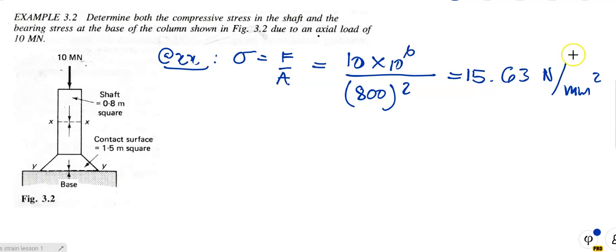There we go. So the stress anywhere along the plane here, along this bit of the shaft of these dimensions, will be that. Have you thought about what it is going to be at YY? What do you think the stress is going to be along plane YY? If this is going to get bigger and that's going to get smaller, we expect the answer to be smaller. That's right. If there's more area, the stress will be reduced on the fibers there.